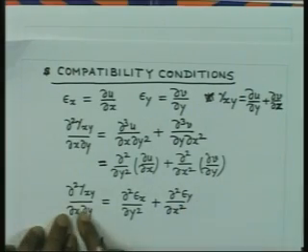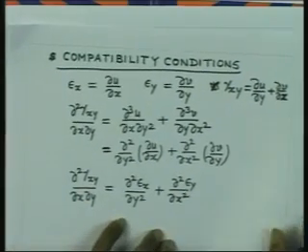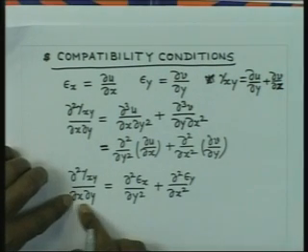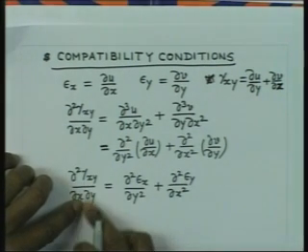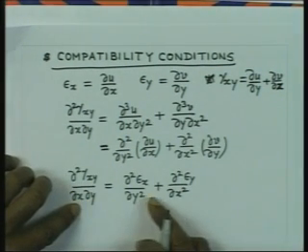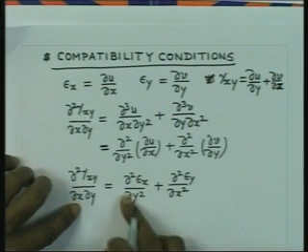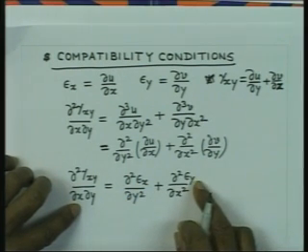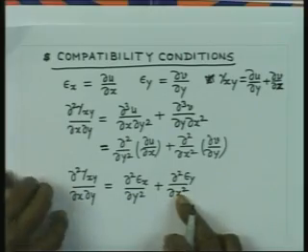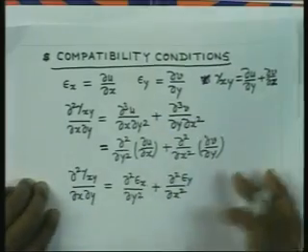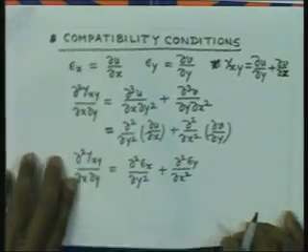So, therefore, this is the compatibility condition. You see that here we have the derivative x y and this is the shear strain, and it is related to epsilon x and the derivative is twice with respect to y, and here it is epsilon y and the derivative is with respect to x. So, this is known as the compatibility condition, strain compatibility conditions.